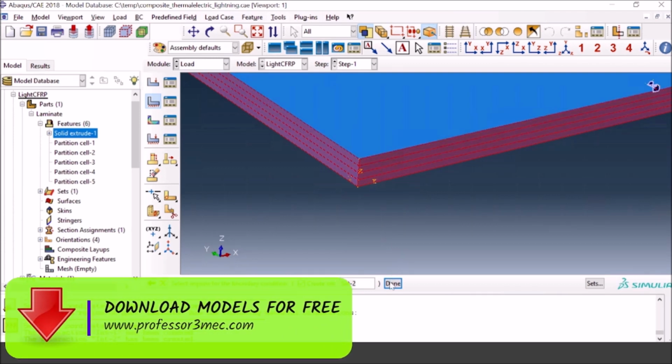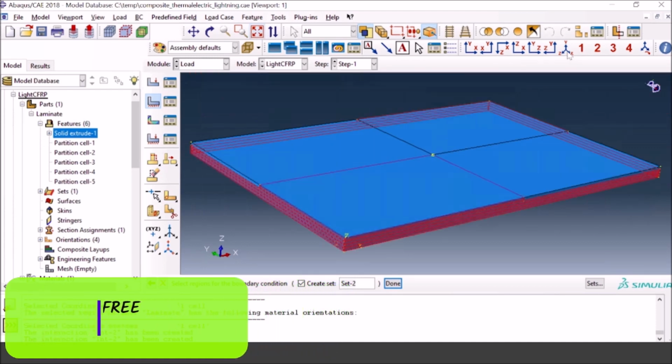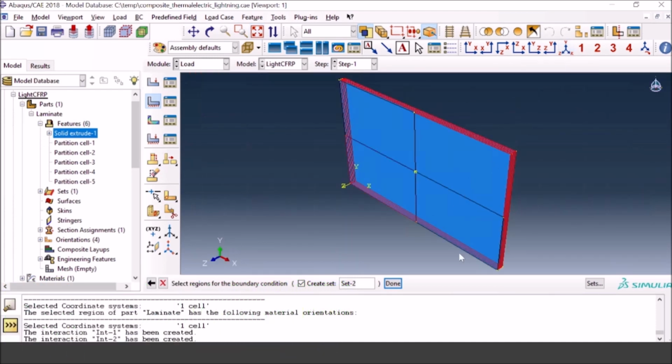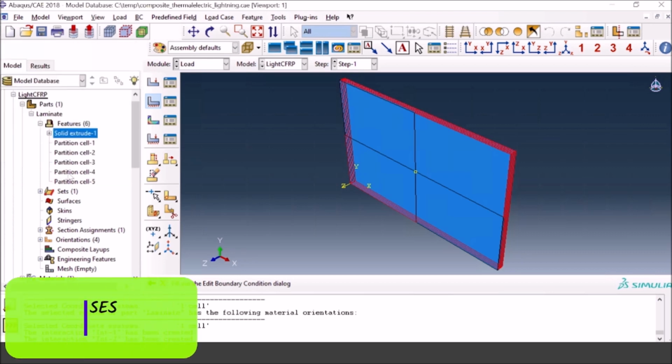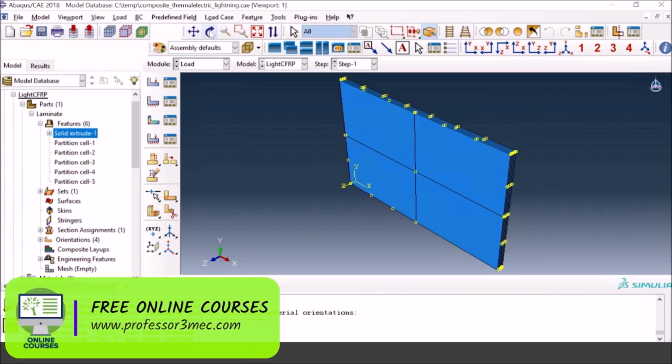There you go. So hopefully these external surfaces, which are the side surfaces, are selected, and we have defined a potential there. If you select internal surfaces, that may cause some errors within the numerical values you get for temperatures, etc. So make sure that you select that. Now I'm giving the value of 0. So now everything is correctly defined, I think.